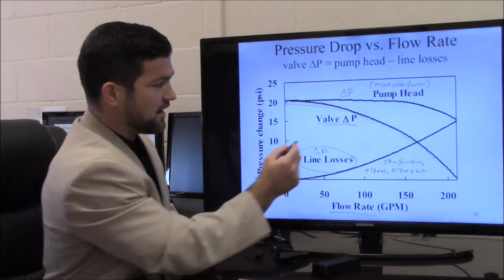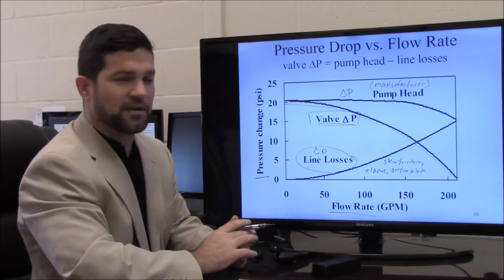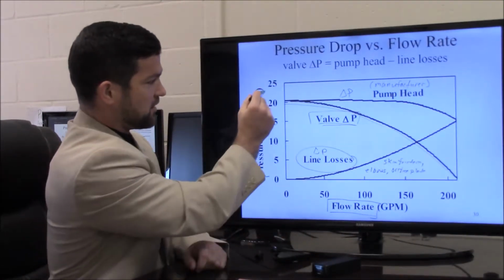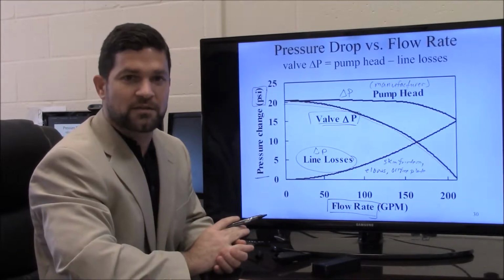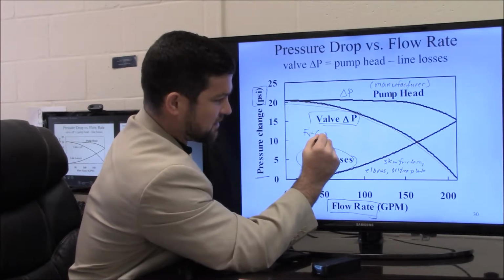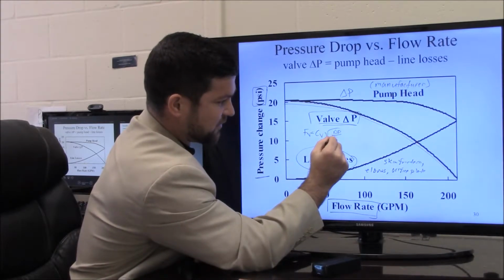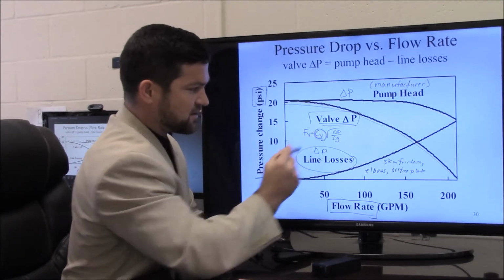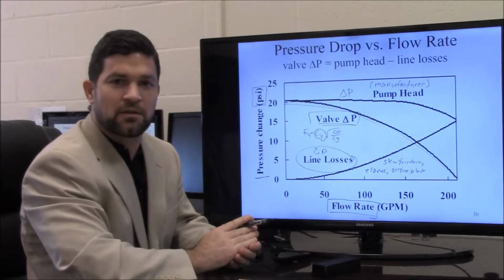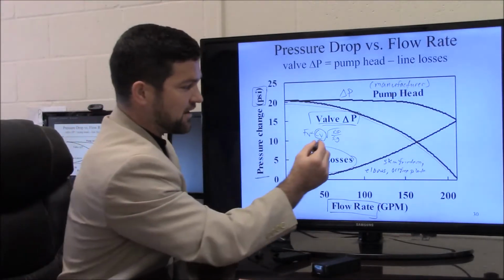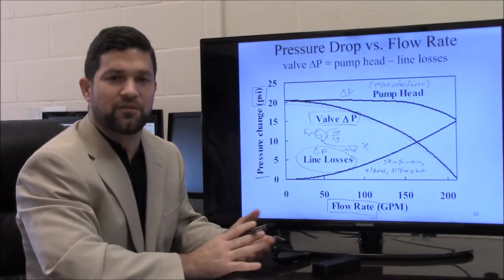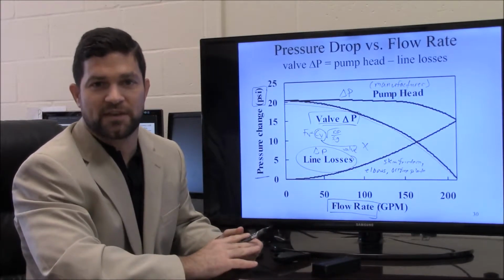Okay, so the next thing we want to do is follow the same process that we used last time. Here we have a valve delta P, and down here we have flow rate. And good, we have things in our proper units. So using this, we can use our equation F_V equals C_V times the square root of delta P over SG. This will allow us to calculate C_V over this whole range of flow rates. Using the calculation of C_V, based on the valve, we can get X. For the linear valve, it's straightforward. For the equal percentage, we'll use the table.